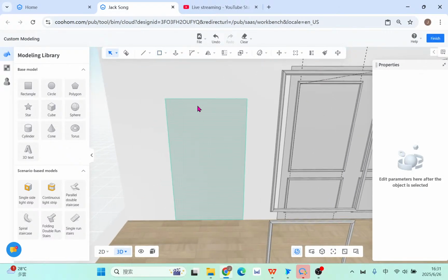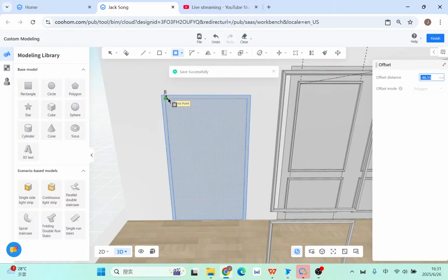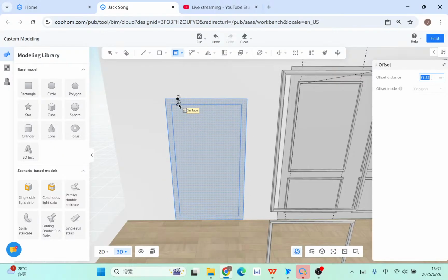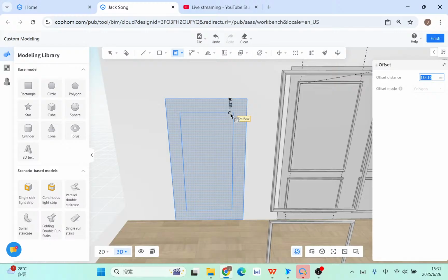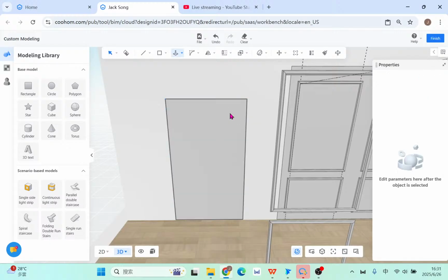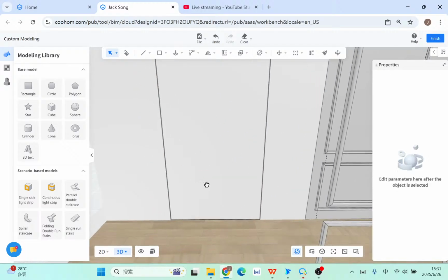And then what you need to do here is the offset. Click, move your mouse. You see, now it's moving. Okay, you can just click within that. This is the door opening gap. For example, the gap is really thin. For the offset distance, you can't just directly give a really big one. Okay, small. Let's say 5 millimeter only. Okay, and delete the center.